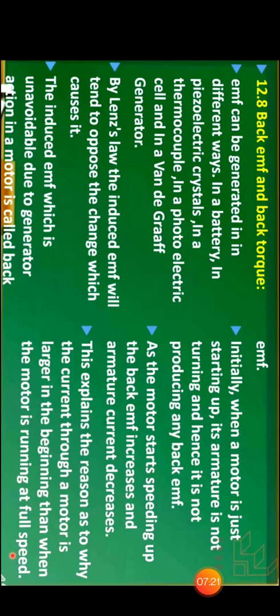In the present case, the cause is the current through the armature. Therefore, the induced EMF will tend to reduce the armature current. The induced EMF, which is unavoidable due to generator action in a motor, is called back EMF.